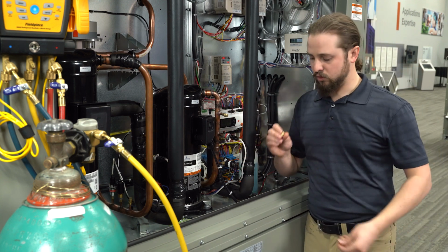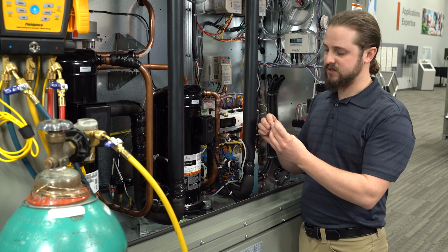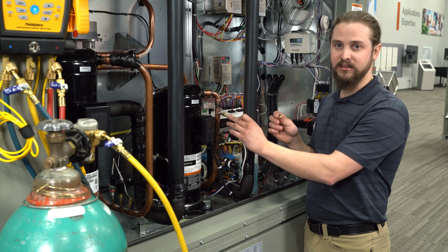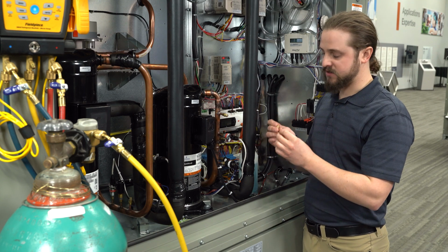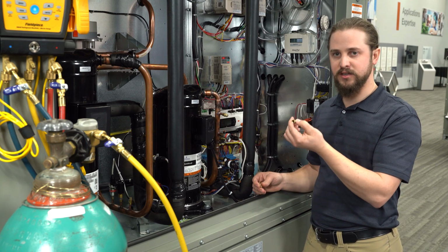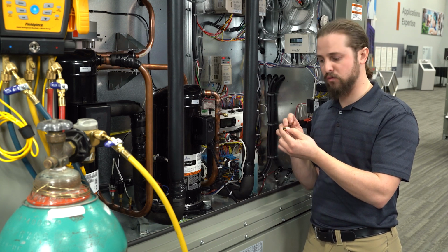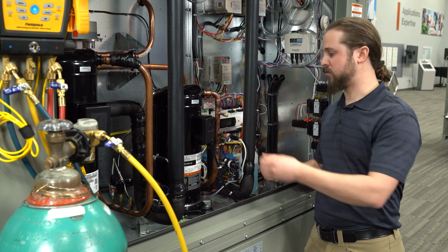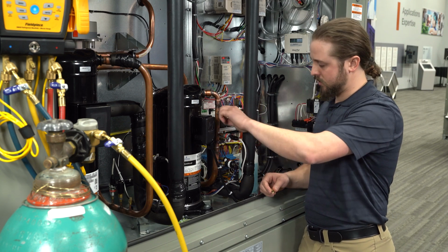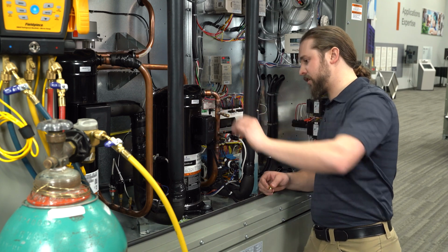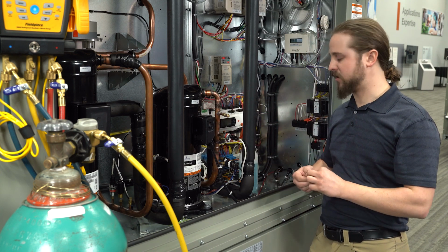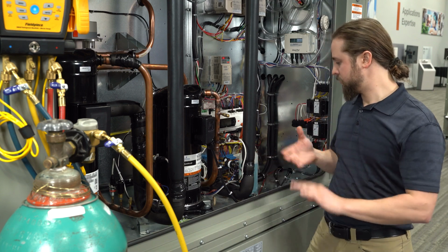Next step will be looking at that cap and making sure that there is an O-ring inside. Now, whether or not you detected a leak through your Schrader core, it's still possible for that core to leak if there's a missing seal. It's always important to make sure that that O-ring inside the cap is present. This one has an O-ring, so we're going to definitely use that. If any caps do not have O-rings, you're going to want to just dispose of them and install new caps with O-rings.